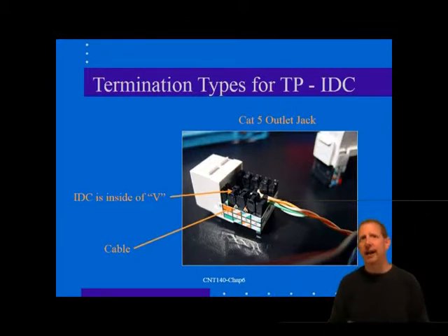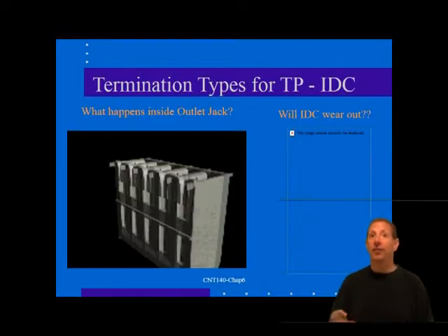The connector contacts mount directly onto a printed circuit board, which also mounts the modular connector. The wires are each cut to size and placed in a channel above the contact edges. A plastic insert is used to push up to 4 individual wires into the jaws of the IDC contacts, where the insulation is pierced and the electrical connection is made between the wires and the contacts. The insert usually snaps into place with a click, which is why we're calling it a snap-in connector.